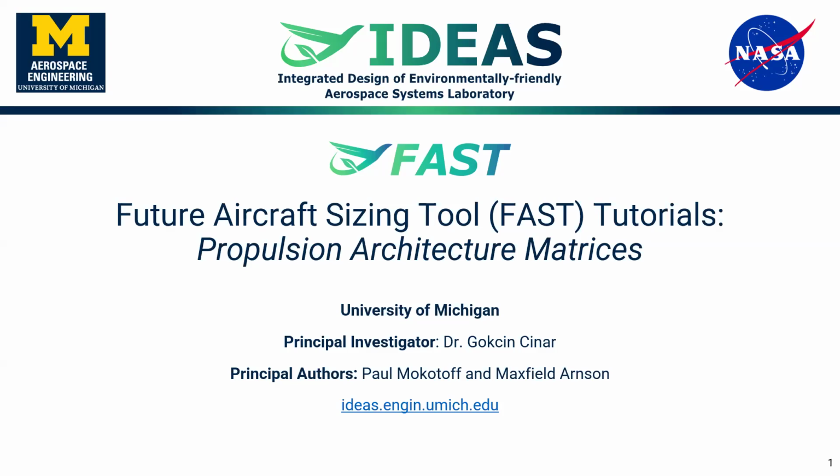One of the things that we haven't touched on yet is how to prescribe a propulsion architecture that is not shipped with FAST. FAST provides 6 different propulsion architectures: a conventional, electric, fully turboelectric, partially turboelectric, series hybrid, and parallel hybrid. But what if you want to make a propulsion architecture on your own? The answer is you have to use these propulsion architecture matrices that I'm going to show you.